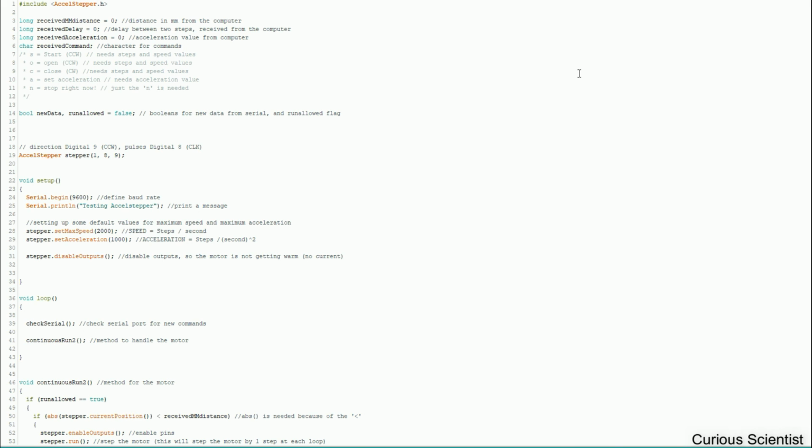Welcome everyone. In this video I'm going to show you how to control your stepper motor by using an Arduino and a TB6600 control circuit and the AccelStepper library. This library is very good because it's very powerful and very flexible. You can control your stepper motor in many ways, and you don't really need to struggle with a lot of things.